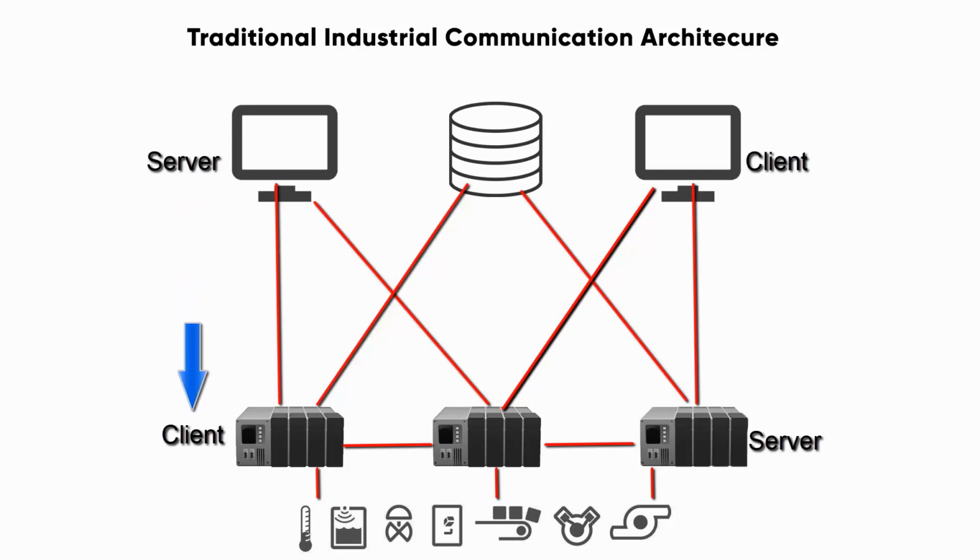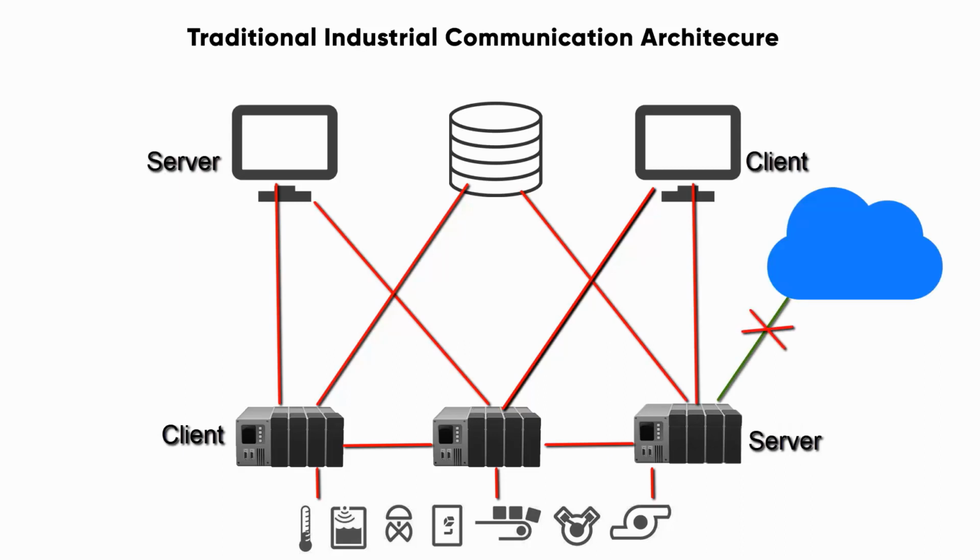What's worse is that this client-server architecture is in most cases implemented using proprietary application interfaces only known to and provided by device vendors. Unfortunately, this means that applications become dependent on a particular device they control. You cannot remove a device and replace it with one from a different vendor, not without providing protocol implementation details. And of course, you cannot access the device data using some cloud-based analytics software that has no knowledge of industrial communication protocols. Such a communication architecture is said to be tightly coupled.